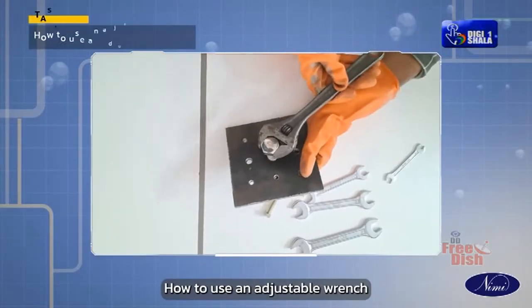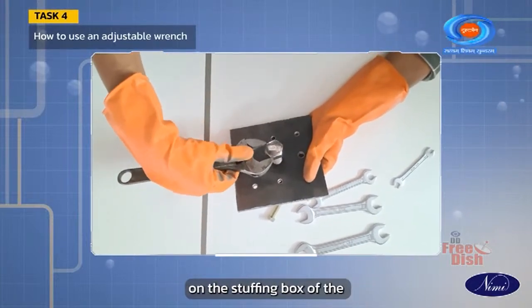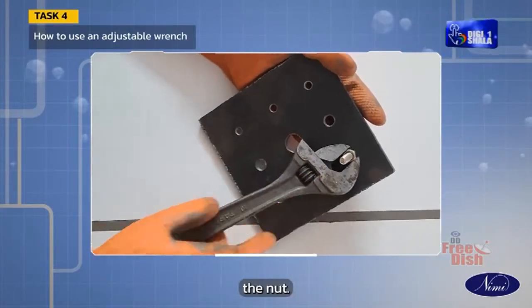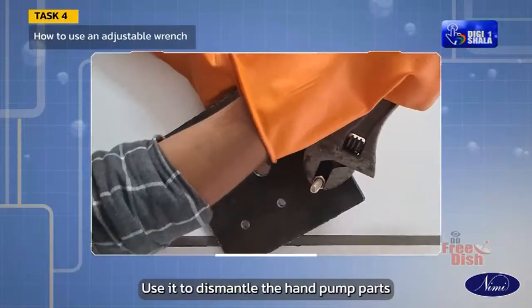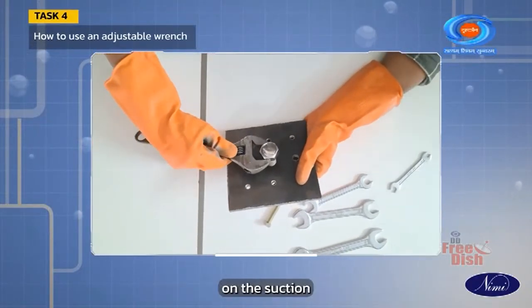How to use an adjustable wrench. Place the adjustable wrench on the stuffing box of the bib cock. Grip and work to tighten or loosen the nut. Use it to dismantle the hand pump parts. Use it to assemble flange bolt and nuts on the suction pipe.